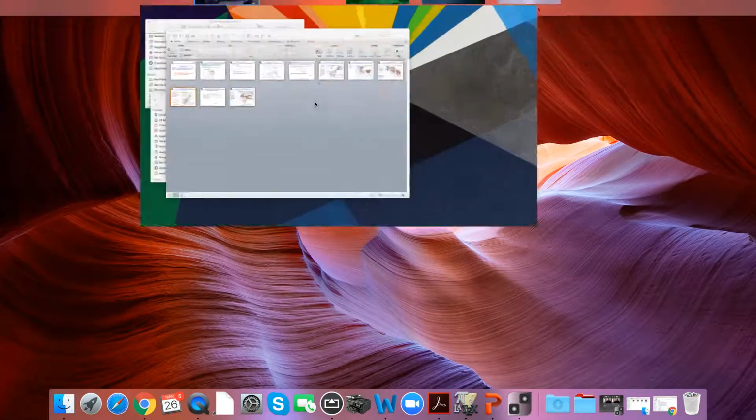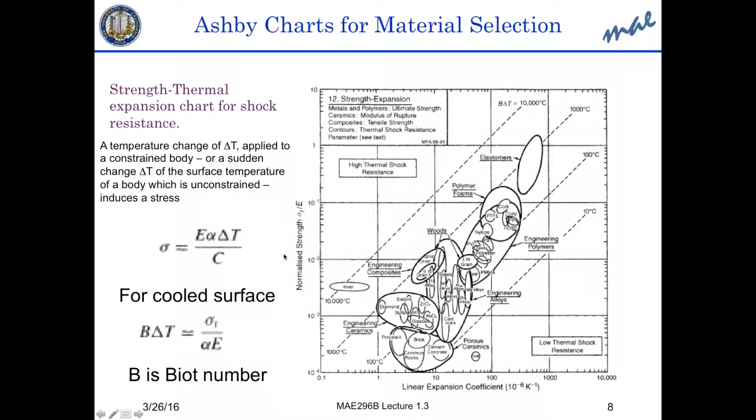So this is during the turning on of a device, for example, like an engine. Therefore, we need materials that do not crack during that transient period. So the rate of cooling is important during the transient period. And therefore, we can describe this thermal shock resistance by a measure which is the delta T that causes cracking.